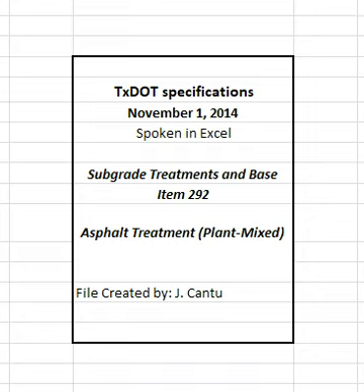Roll the tack coat with a pneumatic tire roller unless otherwise directed. The engineer may use TEX 243F to verify that the tack coat has adequate adhesive properties. The engineer may suspend paving operations until there is adequate adhesion. The engineer may waive the requirement to place tack coat.